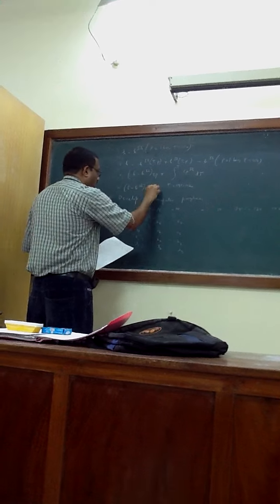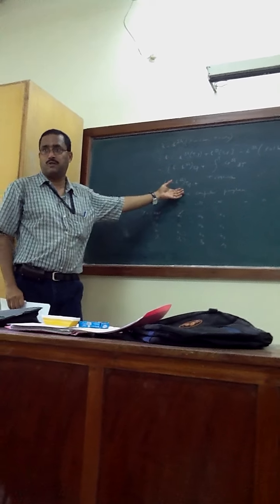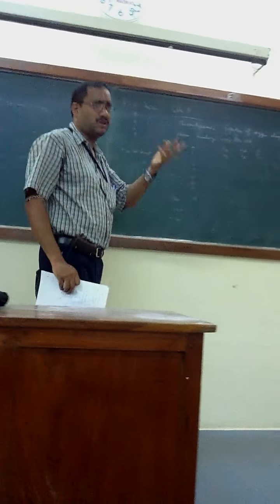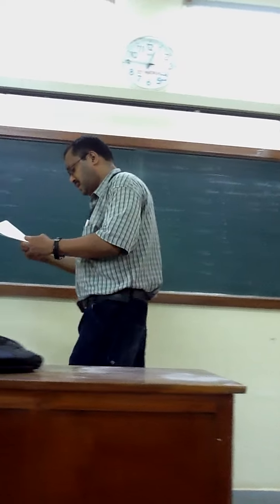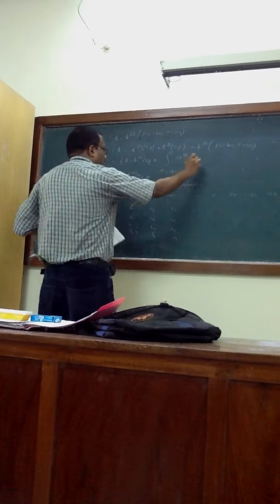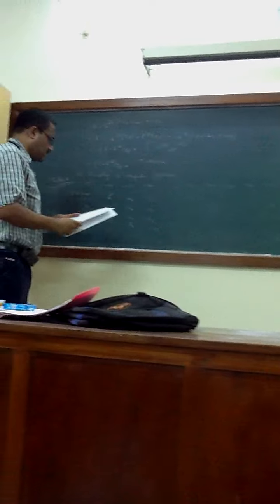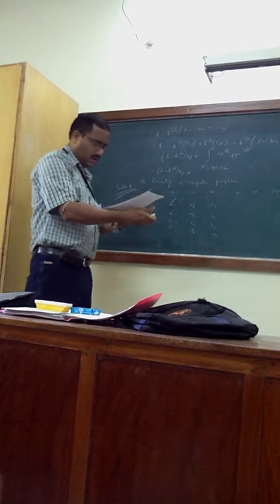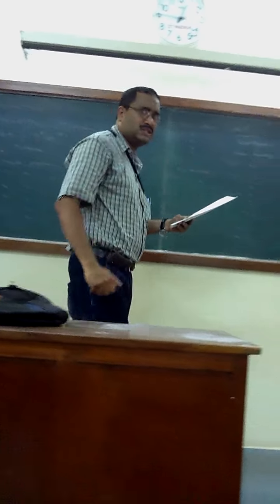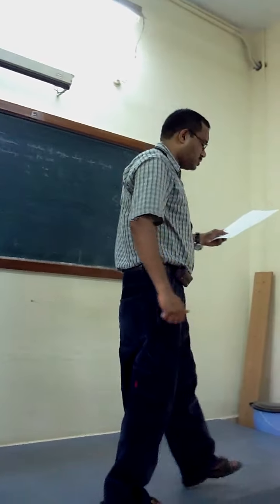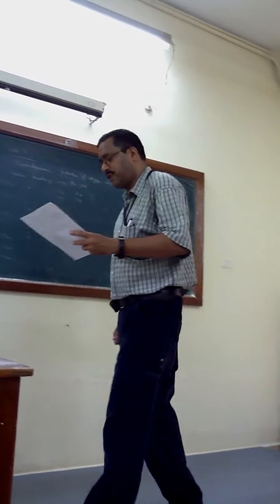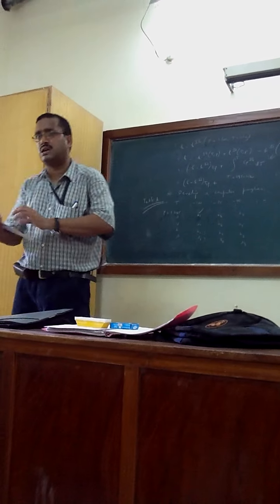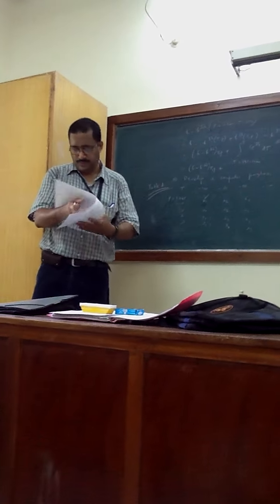Already you have the formula handy, and this formula we derived today in the class for Peng-Robinson. This formula is derived in terms of Z minus 1, and Z is calculated from table A. And you get this new term, Cp^ig, for which the formula was given today in the class: 25.46 plus 1.519 times 10 to the minus 2 T minus 0.7151 times 10 to the minus 5 T squared plus 1.311 times 10 to the minus 9 T cubed.